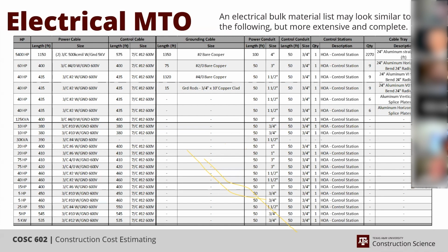That's important because they're quantifying the materials for you here, but there are things that they aren't quantifying, such as your terminations. So if you know this is 400 feet of that cable, that's basically 1 run, while here there's 2 runs. So you would have 4 terminations on each end, twice. So that'd be 16 terminations instead of just 8. By knowing how to read this, you can figure out how many terminations you need, because that won't be in your unit labor that you would apply.